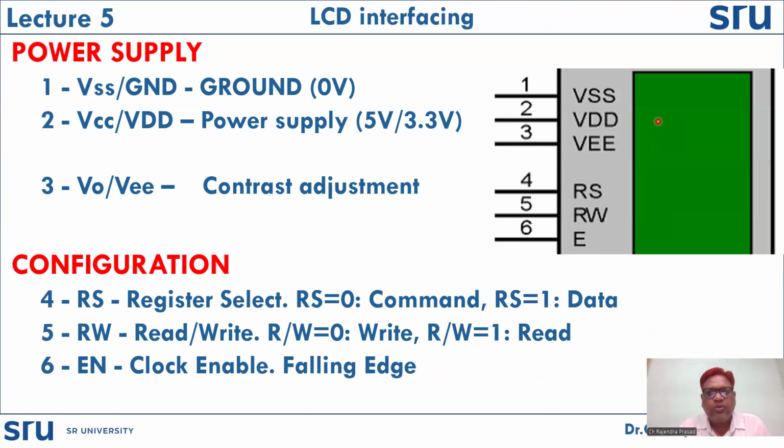So whenever it is connected to any microcontroller or any device, this bus is always trying to draw current from the source. So for battery operated systems, it automatically increases the power consumption. In order to relieve the system from this burden, we enable the data bus whenever it is used, and whenever we are not using it, we disable that bus. That's why this enable signal is provided on the LCD.